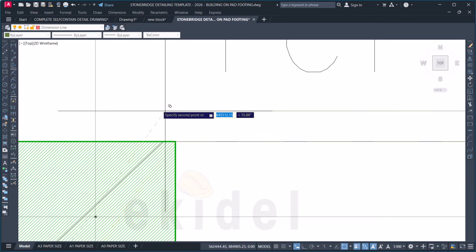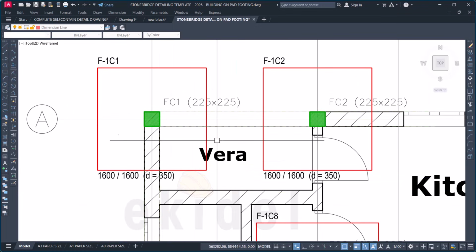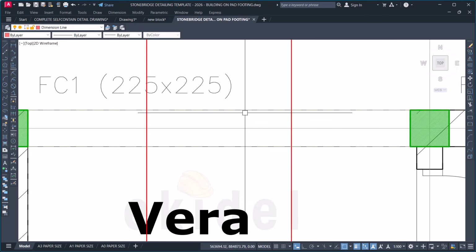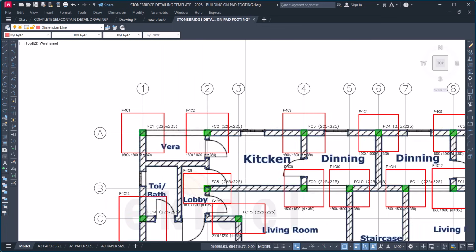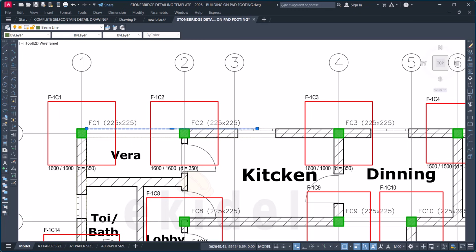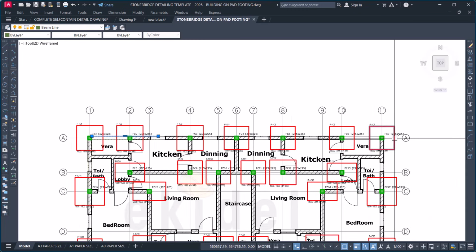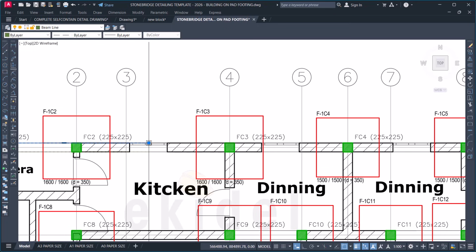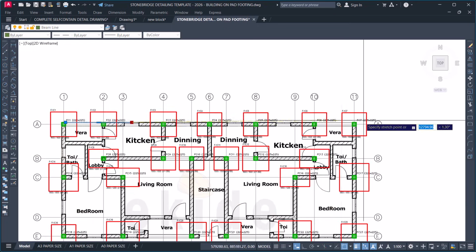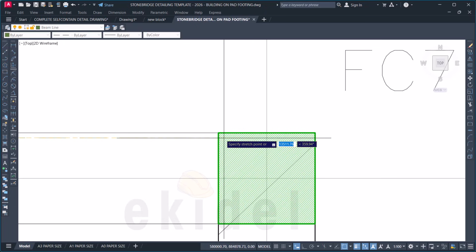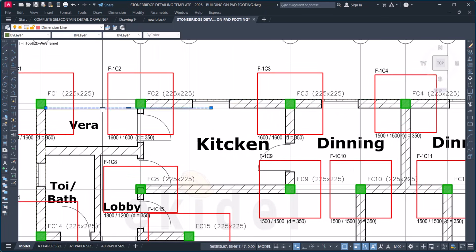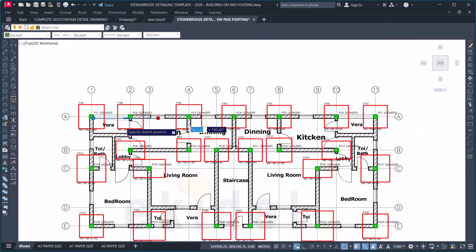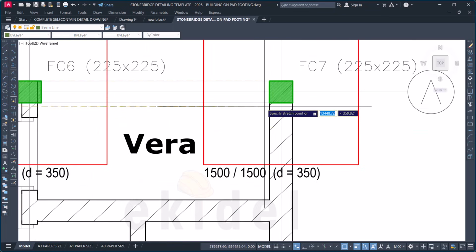Okay, that is fine. So now I have this, although you may not be able to see it, I can. Can you see that? It's showing a dash line. Once you have pasted this, the next thing is to extend this to the end, knowing that the block wall runs from here all the way down here. So I'll click here and extend to this place, and also click on this, extend it here, and then click Escape.